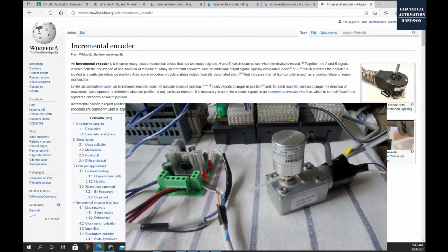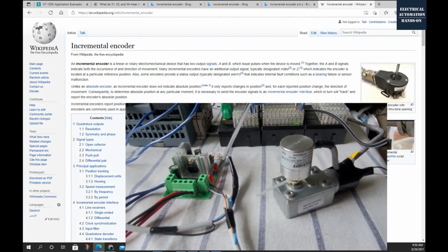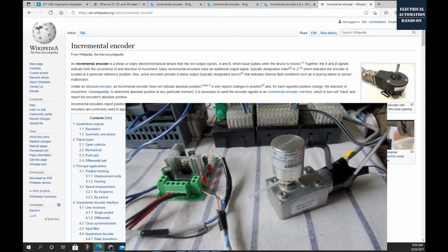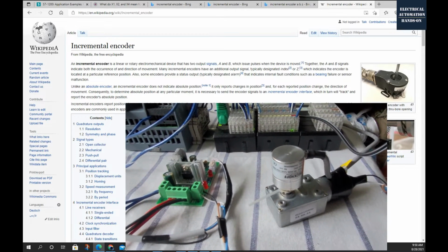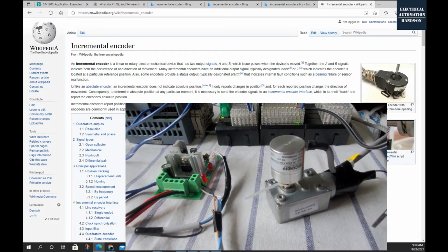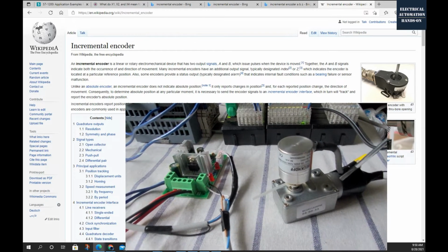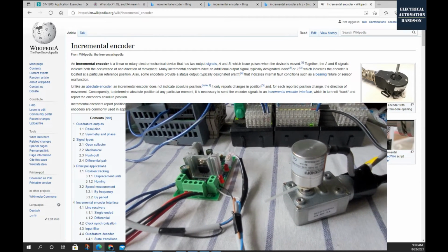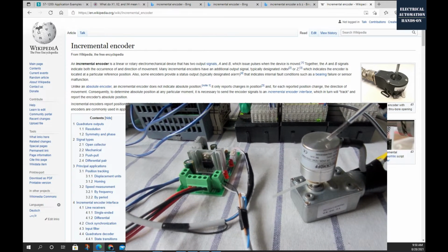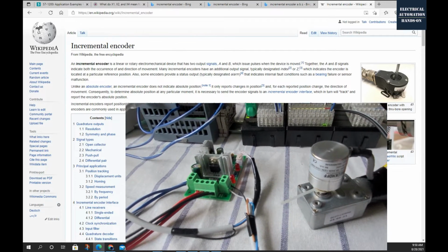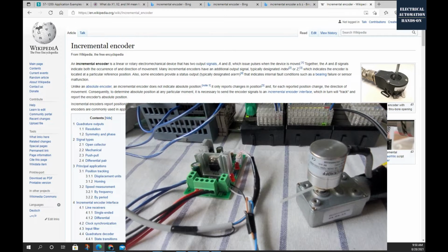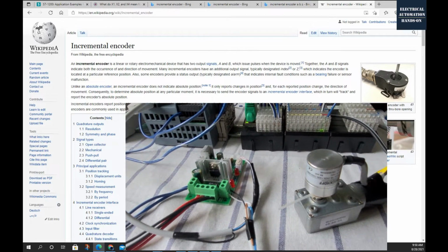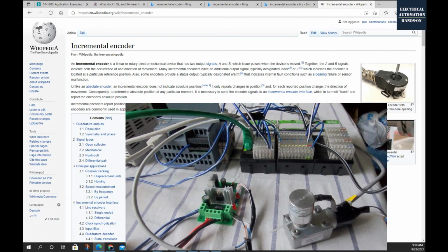And I can use the analog output, use this module to control the speed of this motor. And in this test, I will run this shaft basically 1 revolution per second, so after we read the incremental encoder calculated value, we can verify that the revolution per second should show around 1. So this is the basic idea for this test.